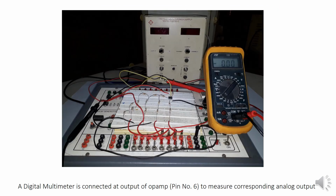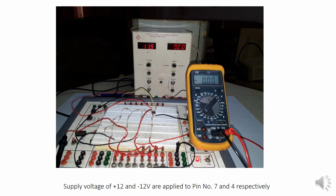Next, this is the full circuit setup. We are going to use a multimeter to measure the output response of the circuit. The multimeter is connected at pin number 6, which is the output of the op amp. Now let us apply power. Here I am applying 12 volts for both channels, 12 volts for VCC and 12 volts for VEE.